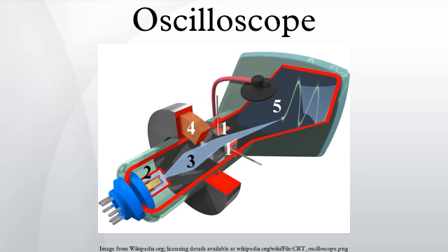The XY mode also allows the oscilloscope to be used as a vector monitor to display images or user interfaces. Many early games, such as Tennis for Two, used an oscilloscope as an output device. Complete loss of signal in an XY-CRT display means that the beam strikes a small spot, which risks burning the phosphor. Older phosphors burned more easily. Some dedicated XY displays reduce beam current greatly, or blank the display entirely, if there are no inputs present.